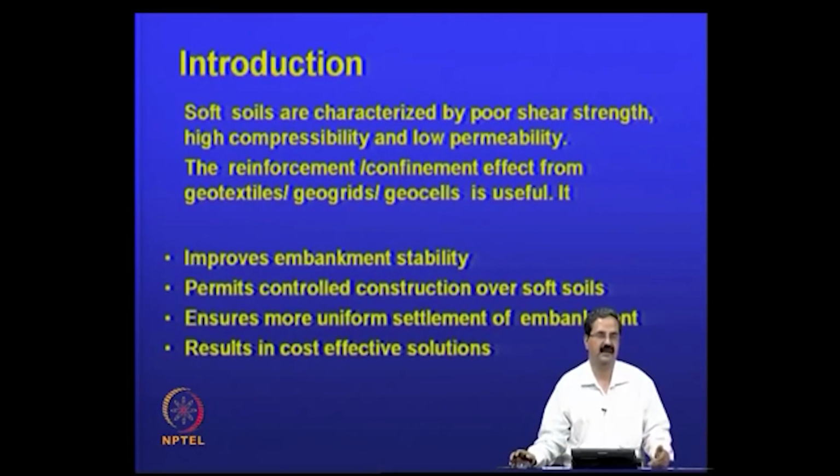We have studied that using the concept of Mohr circle earlier. You apply load and it deforms vertically and horizontally, but if you place a reinforcement, it does not deform that much. That effect we try to equate to an equivalent horizontal stress. That can even be obtained by a geocell.